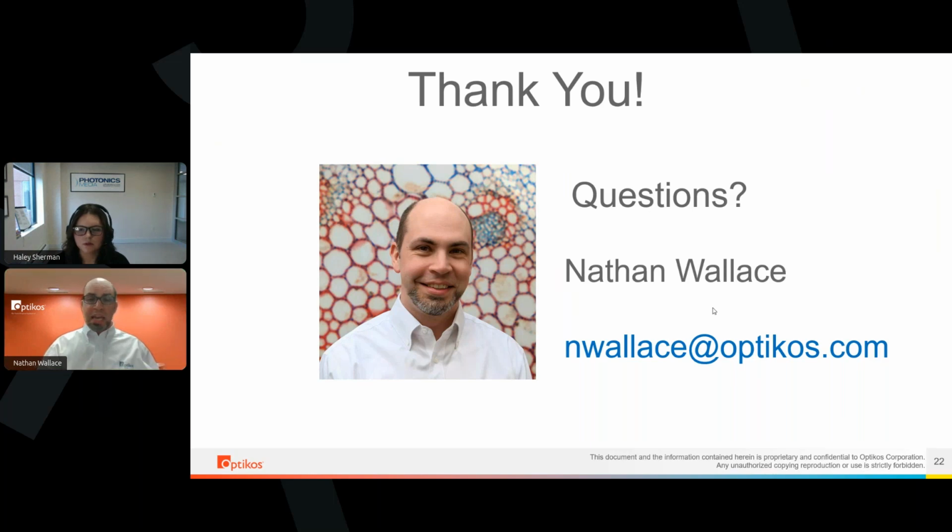to have an issue. And if you find yourself in a situation where you're making an adjustment and articulating the spring, and taking a look at your SN curve for fatigue and things like that, you may want to look at some alternate materials for that spring. Maybe something that has just a longer fatigue life, things like that. Hopefully, I answered that question well. It's a very interesting one.